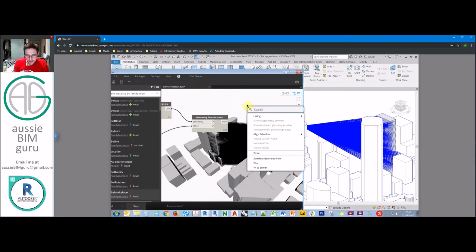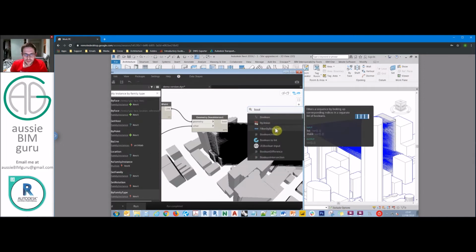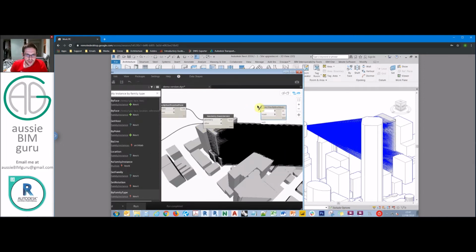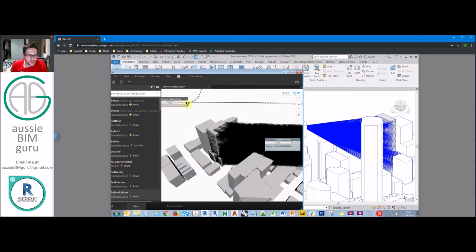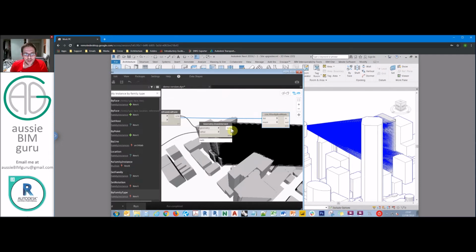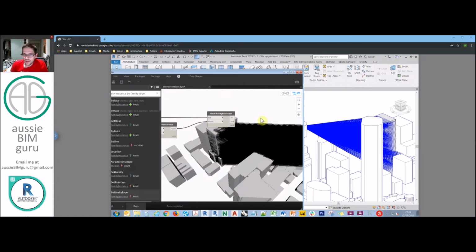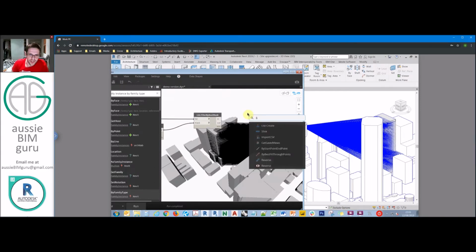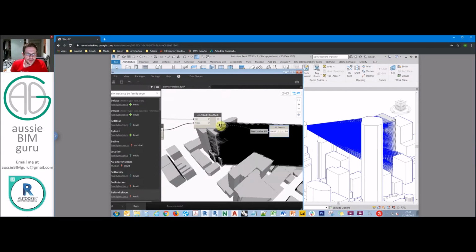But we're going to do a Boolean mask after that. And we're going to go back and filter our families. So we're going to say we only want the sensors that don't intersect with the site. So we're going to just mask based on the intersection. And we're going to take our out list. And our out list would represent all the lines that don't clash with anything.